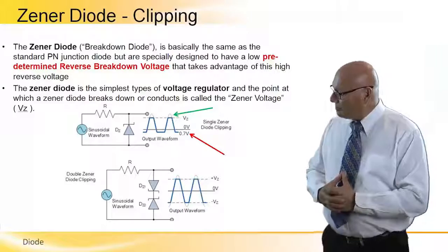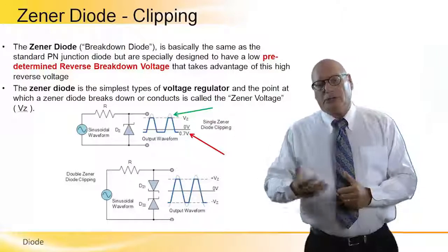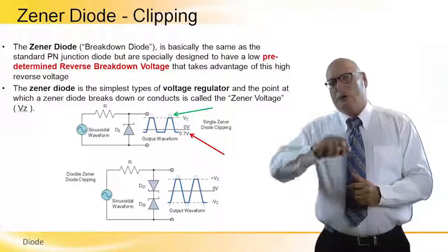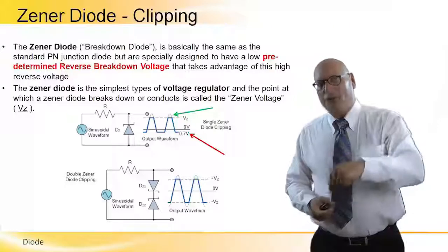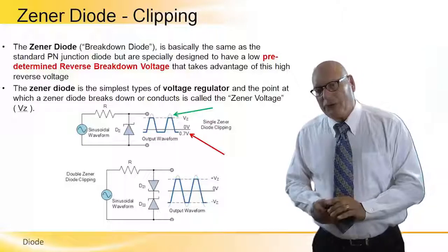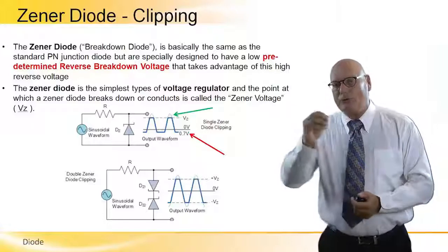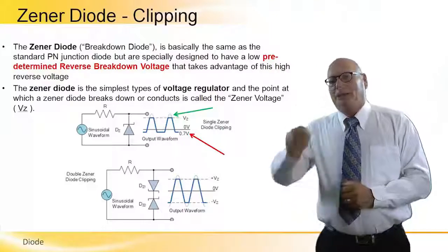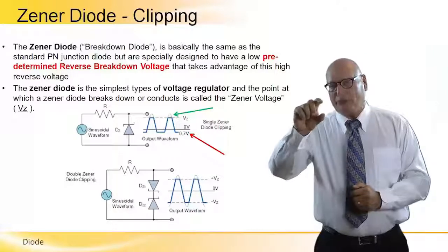Let's actually evaluate what's happening in the top one. We have an AC generator that generates a sine wave. And this sine wave, on the positive side, goes through a resistor, in reverse direction through the Zener diode, and when the voltage level of the sine wave goes above the rated breakdown voltage of the Zener, then the Zener actually breaks down and holds upon itself that particular voltage.